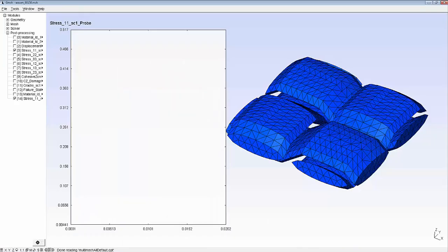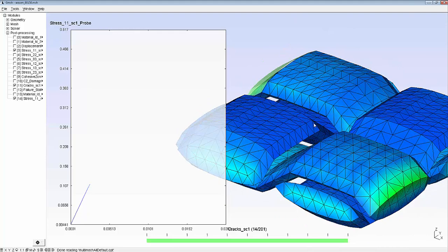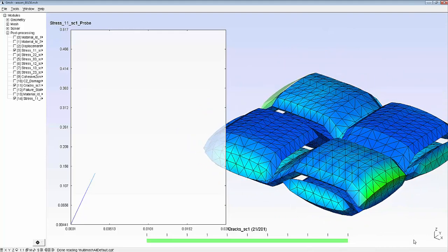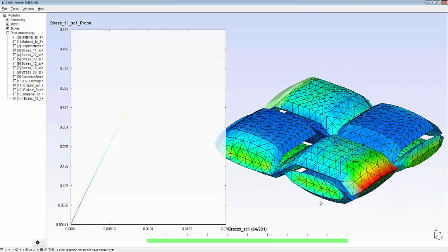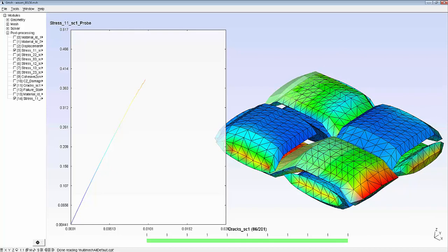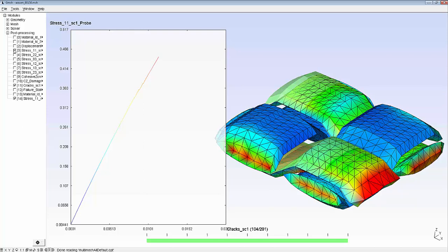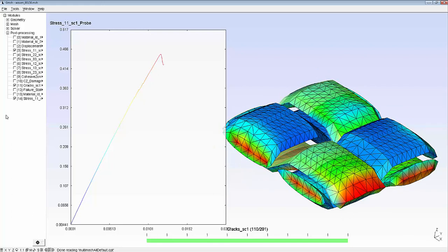Here you see the weave and the stress response within one of its central nodes. You can see that as stress increases, toe ruptures begin to occur, and stress concentrations between the toe and matrix result in debonding. As that damage and debonding occur, the stress within the part is decreasing because the overall stiffness of the part is going down as damage accumulates. You can see the light green regions within that part represent the interface crack between the toe and the matrix. Eventually the part fails catastrophically.